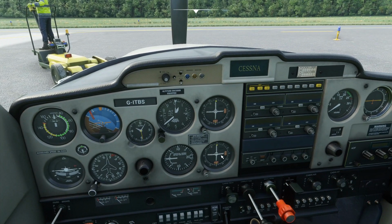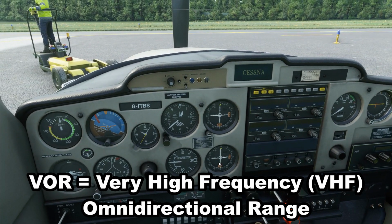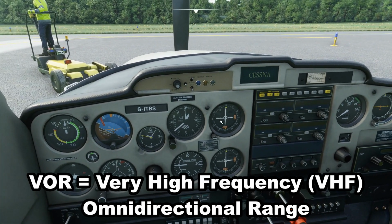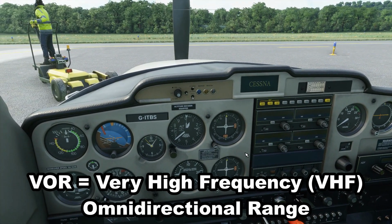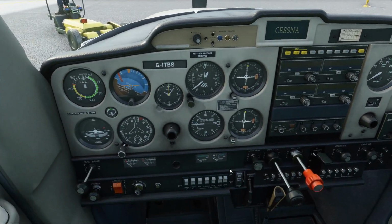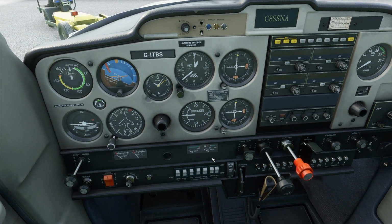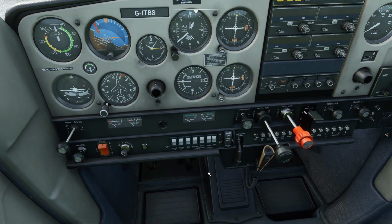To the right then we have two VOR indicators, VOR1 and VOR2. We won't discuss these too much now. The VORs are more related to instrument flying, although it is perfectly acceptable to use them for visual flying as well. Basically we can tune using the radios a ground-based radio navigation beacon, and these instruments allow us to see our position relative to the tuned beacon. Next we have the engine oil temperature and oil pressure. They're used to check that the oil system is working correctly, providing lubricating oil to the engine, and also give a good indication of the general running condition of the engine itself.